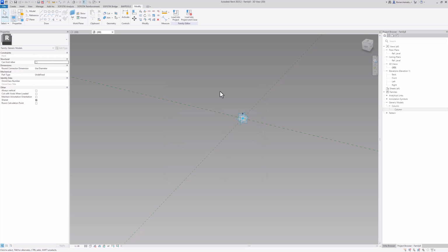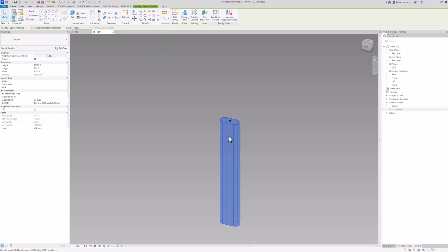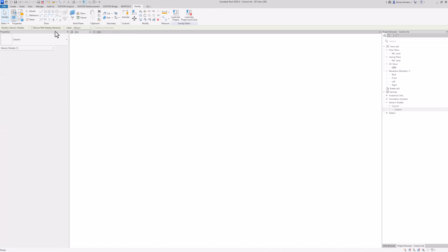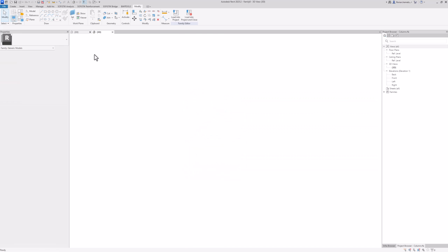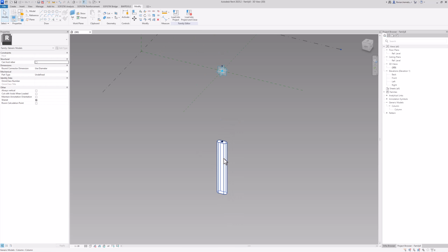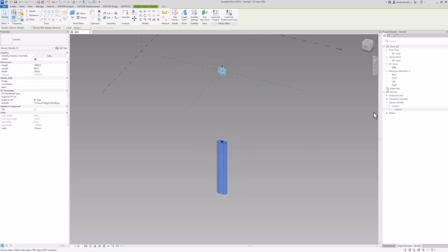And just leave it like that for now, because as you can see, the family that we have here actually does have their own properties, which are on the other hand assignable, and those are the height, length and width parameters that we created in our original family as height, length, width. By the way, we can close this family now. We don't need it anymore because we already have it in this other family as a nested one.